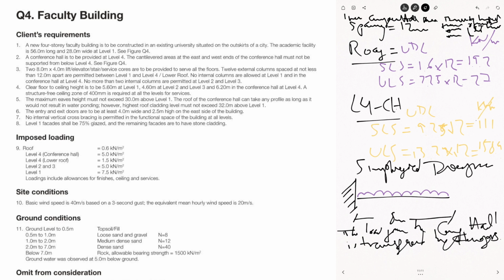In tension. So it will be the equivalent of point loads. But for simplicity, because the point loads are at close centers, we're going to assume distributed as UDL.